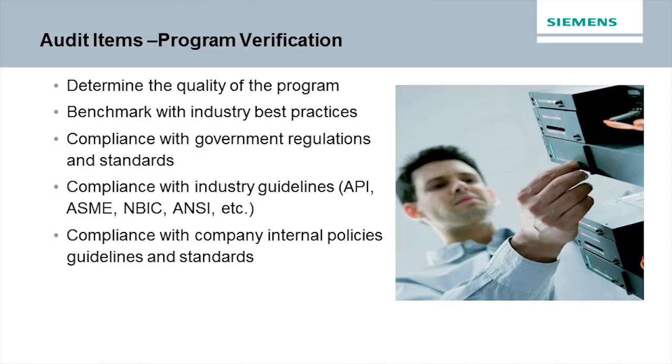Just like PSI from a new project, how are those incorporated into your mechanical integrity program? MOCs: when you can't buy or get the same equipment to replace an old one, what do you do with those? There's PSI, there's an MOC process. Incident investigations: when equipment fails, how are the recommendations followed through and incorporated into our inspection plans, programs, implementation, and so on? So mechanical integrity does not stand alone. In terms of the quality, I'd be looking for those to make sure that the program is evergreen, even though the things around it keep changing, that our program has provision to pull those and incorporate those changes into the mechanical integrity program.